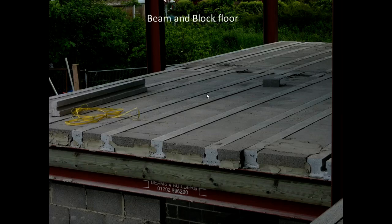This has been a very common way of putting floors together over many years. It's known as a beam and block floor, as you can see there. Most of the loads are being taken by these precast concrete elements, and they're not I sections, are they? They're sort of an upside down T. You can see the T section. That's taking most of the load, and because it's got this slight edge, this flange here, we're dropping in lightweight concrete blocks in between the two to make the continuous surface. It's a very cheap and very simple way of putting a floor together.